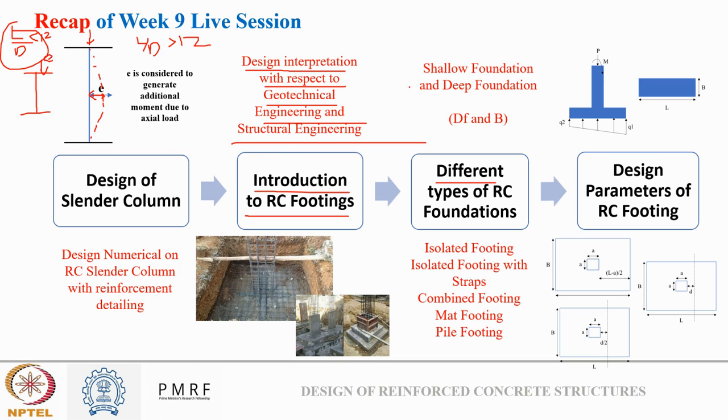The major classification is done based on the ratio of the depth of footing and breadth. If my depth of footing is less than breadth, I say it is a shallow footing or shallow foundation. And if it is greater than breadth, then we say it is a deep foundation. Foundations are a combination of footings, so we can say either footing or foundation. Now, more specifically, there are majorly five types of footings.